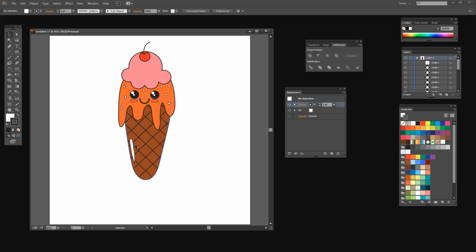And typically when people use this kind of shading, it has a dot on the end. So again, I'm going to select the ellipse tool and hold the Shift key as I create a dot to go on the very end, and I'll just move that into position. Now if you're happy drawing these in place, you can go ahead and draw them in place. I just like to sometimes draw them to one side so I can make sure that they're all right, and just finesse them out to the side and then move them into position when I'm ready.